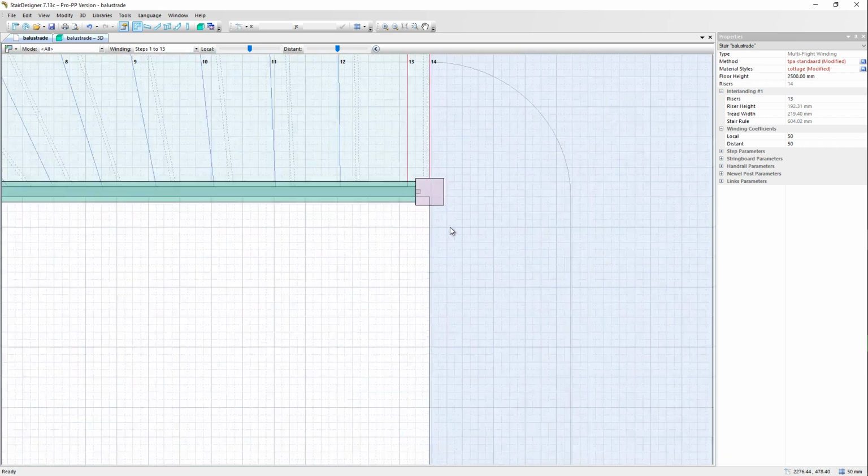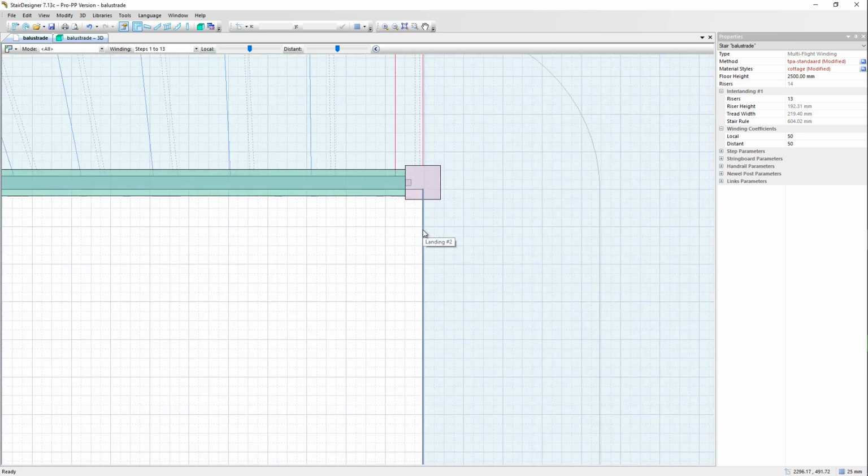In this case, the balustrade will be built up out of a lower rail, which will be created with a springboard. A springboard can only be inside of the stairwell or outside of the stairwell. We need a correction so that it sits centered on the newel. How can we do that? The only way to do it is to make a correction on the well hole.